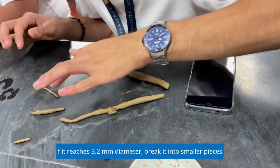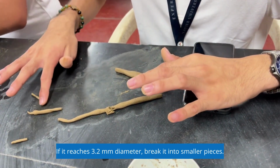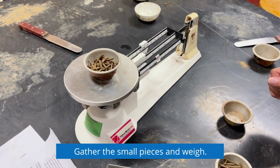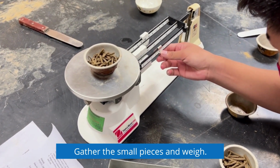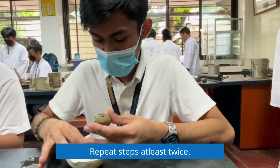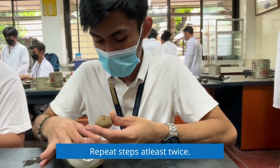If it reaches 3.2 millimeters of diameter, break it into smaller pieces. Knead the smaller pieces and reform them into an ellipsoidal mass. We gathered and placed the smaller pieces into the container. We weighed the can that contained the wet soil and recorded it. Repeat the steps from forming the soil into an ellipsoidal mass to gathering and placing it into the container at least twice.